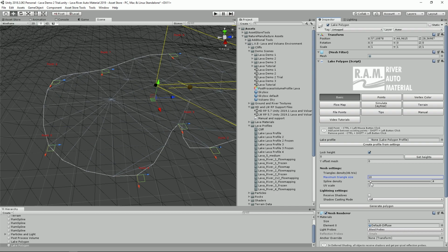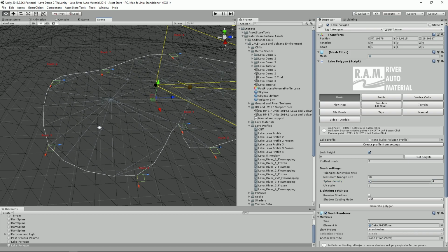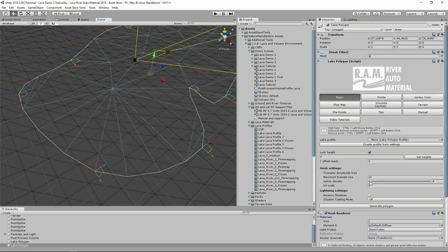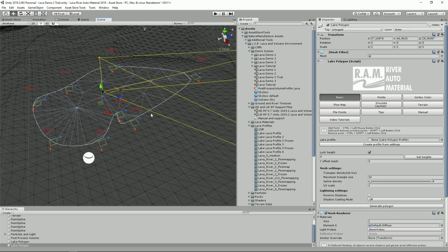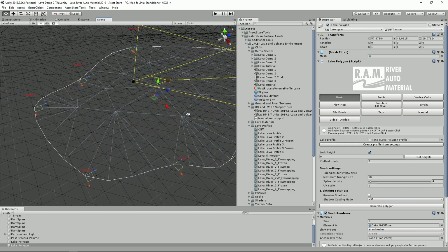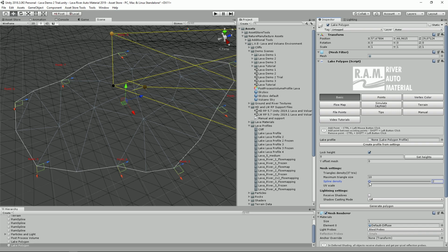For tessellation, we rather try to use equal triangles, because tessellation works best when triangles are pretty equal. So we rather should keep equal verts for tessellation, but if we don't use tessellation, we could use any shape.